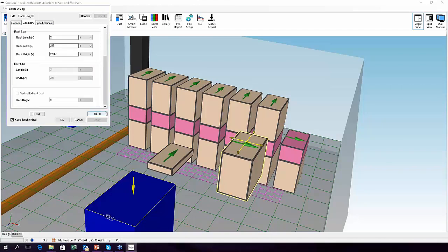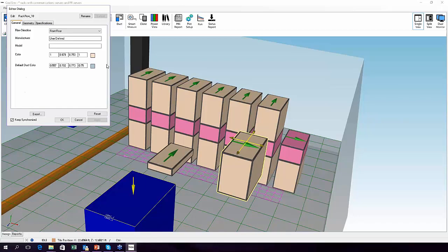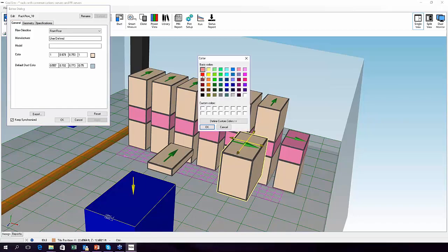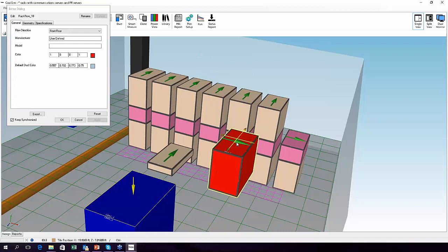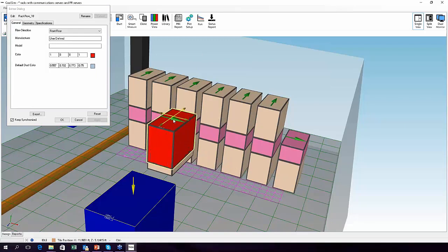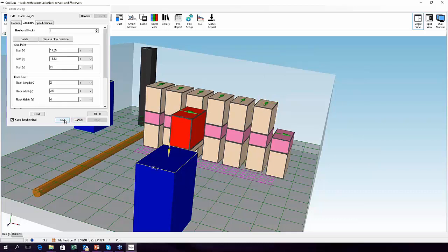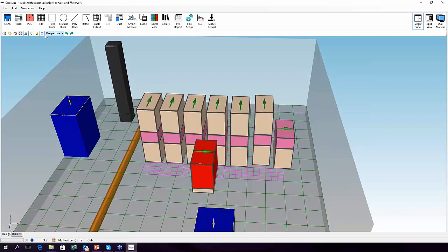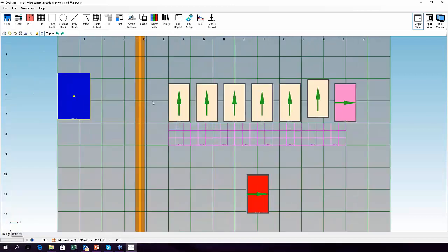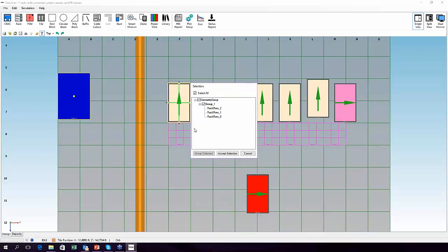By the way, you may want to change its color. Color is under General, just so that it looks a little bit different. And then you line that up on top of this one, and you make a group of them, like I have here, and then you replicate them. So here's the group. Once you have them stacked, then you just group it by drawing a rubber band around it. Again, the best way to group is probably top view. So you take your control key and your left mouse key and you say everything inside that box I want to be in a group.